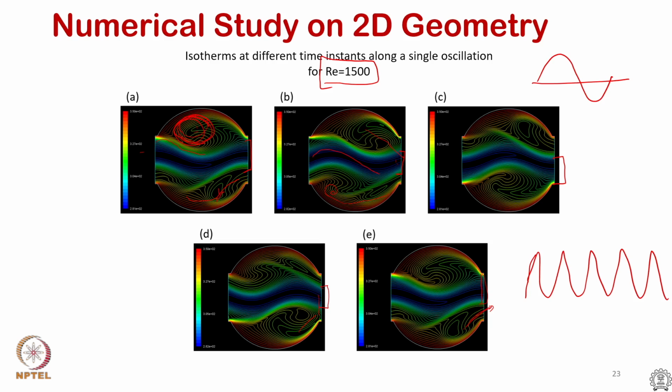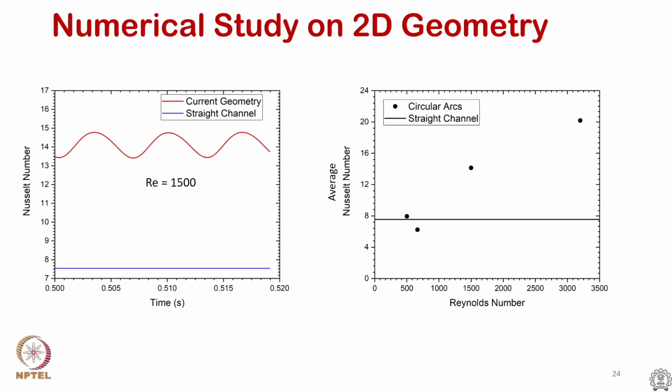But I didn't talk about how much improvement in heat transfer. What you at least saw is that there is an effect of separation created, and the separated zone starts to shed vortices, and that pushes the core flow up and down, and that creates an unsteady flow. So, we will go and look into what the performance looks like in terms of heat transfer.